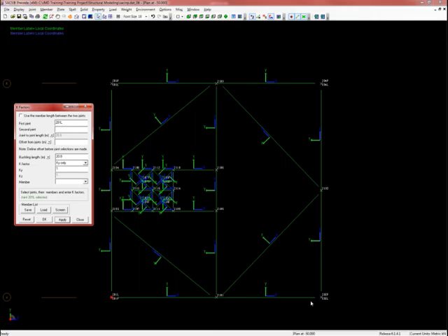We'll do the bottom here, 2 end joints. Hold down control key, pick both members, apply. Then we'll go to the top, click both end joints, and hold down the control key for all the members and apply. Again, on the right, we'll click both end joints, click both members, and apply. So we're then finished with that elevation.